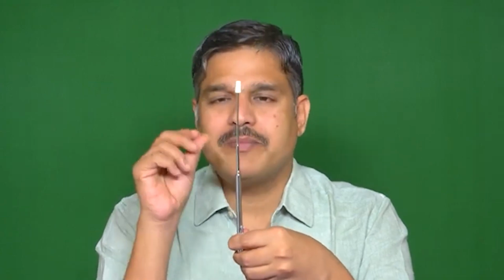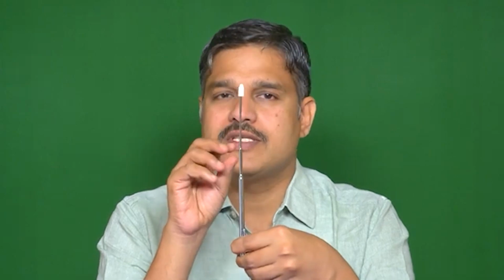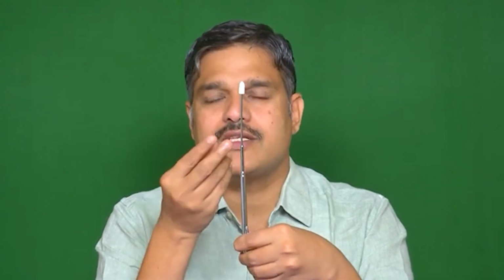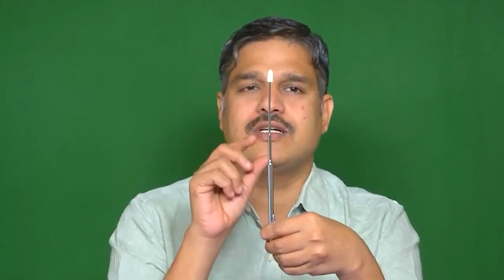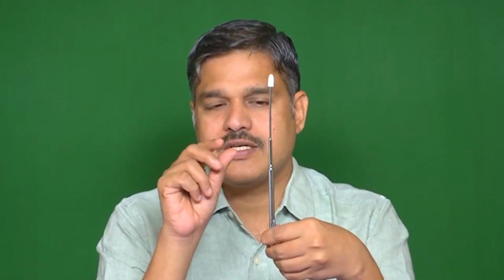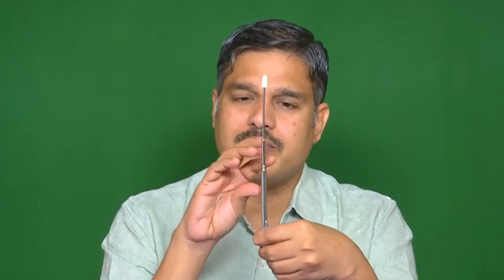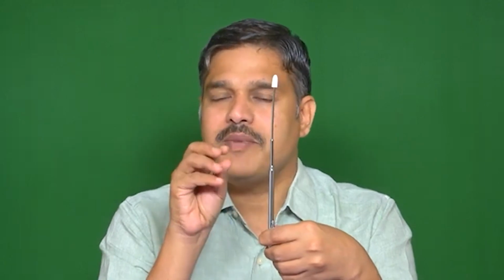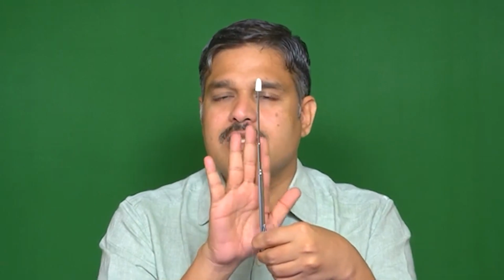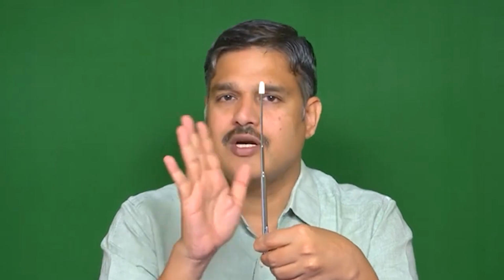So tuned mass damper is tuning the frequency of the secondary structure which we are going to install either on the top or anywhere in this structure, and the frequency of that structure is matched with the frequency of the primary structure. Using these two we will derive the damping which needs to be present in the secondary structure, because the damping already present in the primary structure is insufficient to control the vibration. So this is the main concept of tuned mass damper.